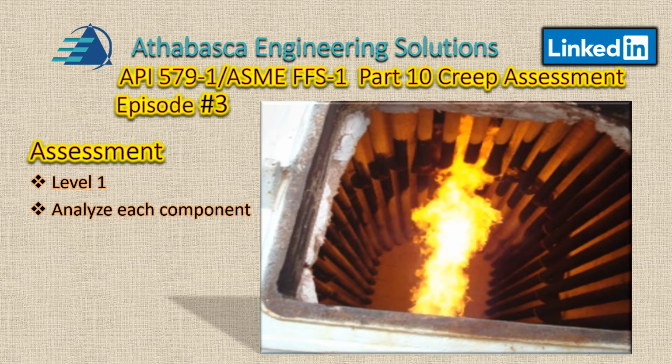If it's outside the firebox, it's cooler, so we consider the tubes to be the worst case. For the purposes of this example, we are going to assume that the tubes are adequately supported and that the circumferential pressure stress is the dominant design condition.